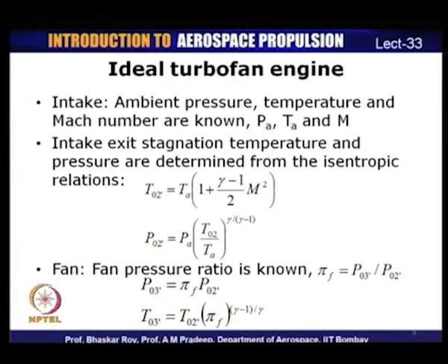P02 prime is the stagnation pressure at the intake exit, which is equal to PA into T02 prime divided by TA raised to gamma by gamma minus 1, which is again a consequence of the isentropic nature of this process.